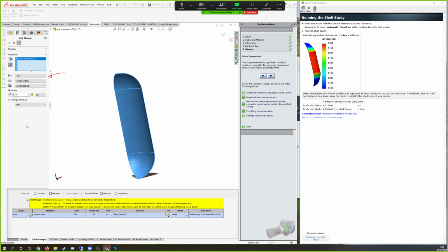Middle surface. So what you can do is change which direction it interpolates from. At the moment we're calculating it through the center of the material, and it'll interpolate the values both ways from the 2D elements. But you can say, start at the bottom and interpolate up, or start at the top and interpolate down. And then you select your material, your thickness, and you're done. That's how you define your shell elements.